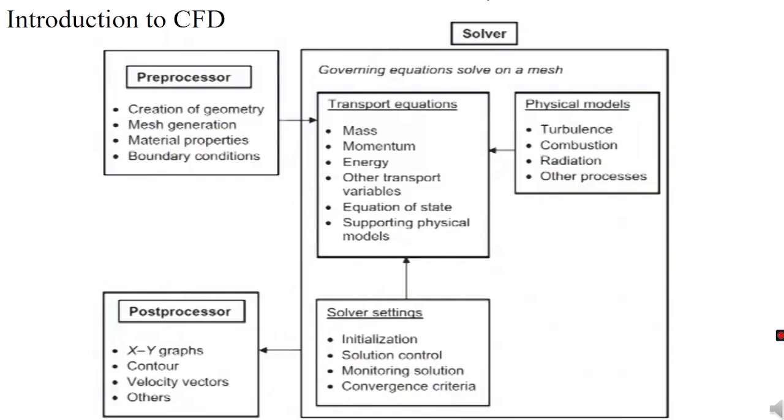Then solver initialization and setting up. Once you have proper initialization, then it is very easy for us to solve and get convergence very quickly. So proper initialization of inlet, outlet, or hybrid initializations influences the convergence speed.